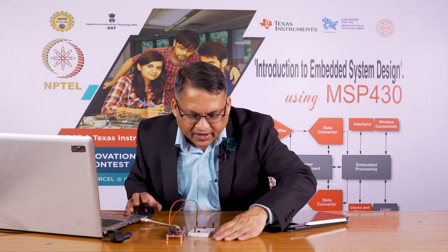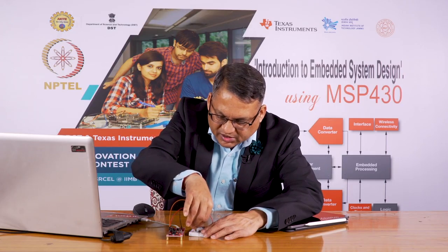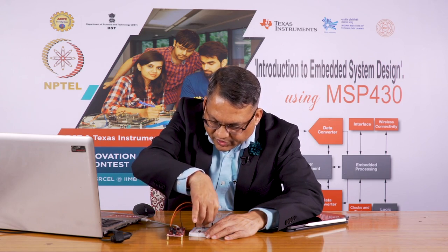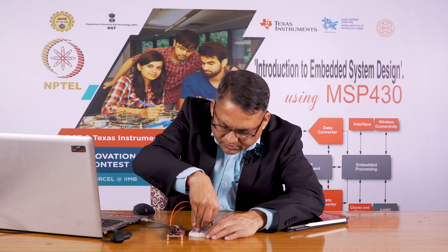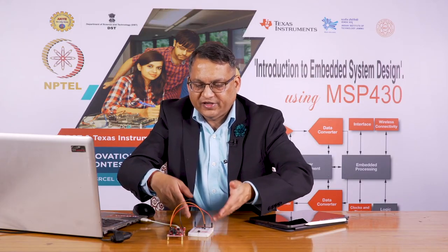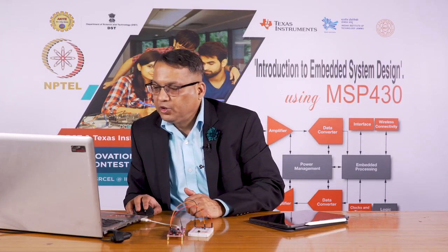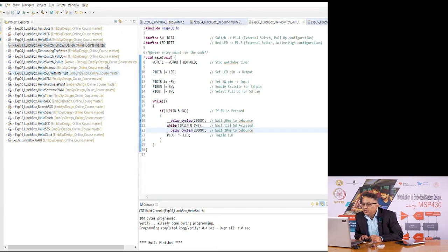I will connect the appropriate switch which is connected to the pull up function, and we will recompile this program here. There are two wires, one to ground and VCC, and the third wire is to an appropriate switch. In this case, the switch is such that it is a pull up configuration. So, we are going to use the internal pull up feature.